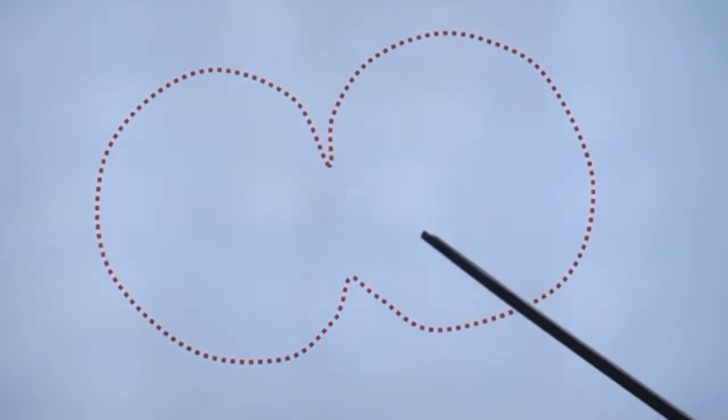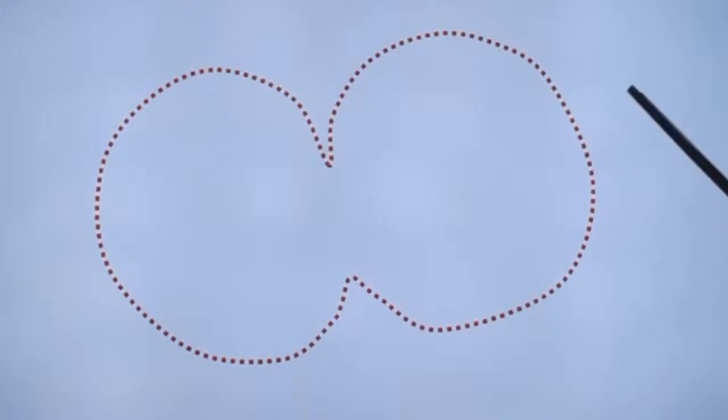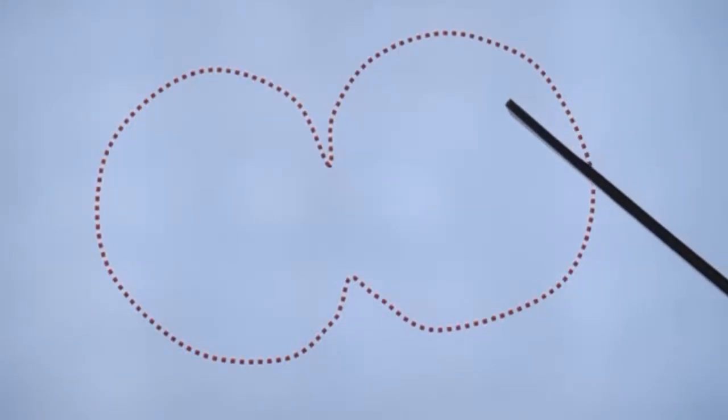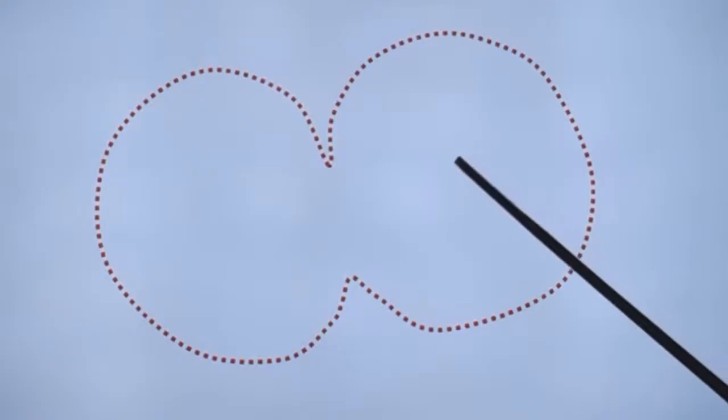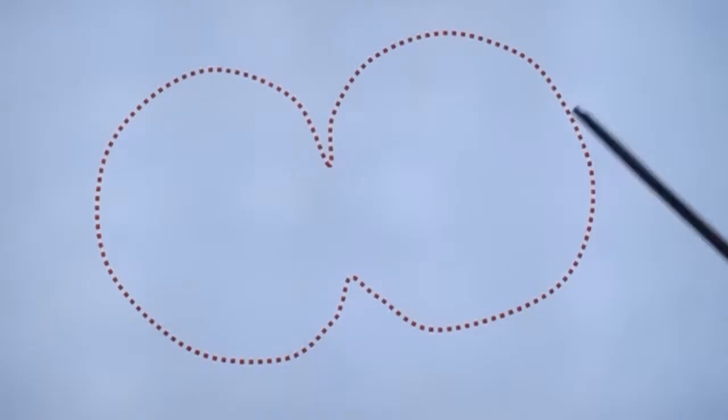This diagram illustrates the radiation pattern from a J-pole. So as you can see, it is slightly higher towards the matching stub region. And a slightly higher angle would mean that it will be directed towards the sky partially, and that is how this is useful in satellite communications. You want the radiation to be slightly on a higher angle towards the satellites in the sky.